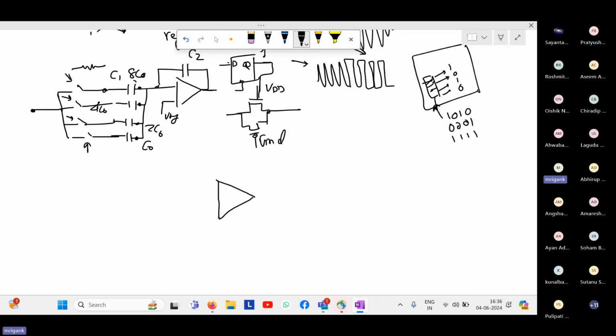This comparator, under normal circumstances, when there is very little signal and seizure is absent, the output of this amplifier will be close to VREF, right? Because under normal conditions, when the signal is very small, or basically there is no seizure, we remember we used an RF feedback resistor to bias this, and that makes sure that the DC level here and the output is the same.